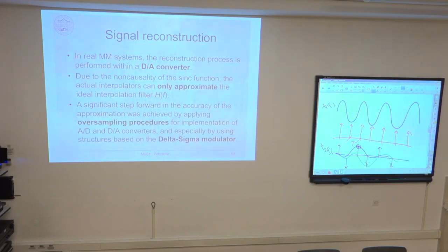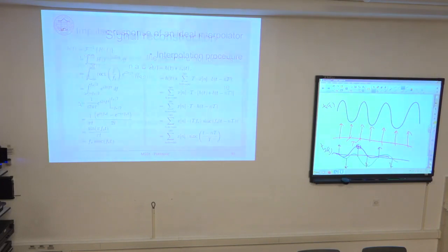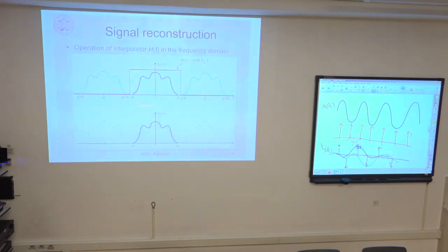So most of the filtering required to do this brick-wall filtering of the spectrum is done digitally, and only the last part is done in analog, with some RC circuit. So they have only a passive filter with one capacitor and one resistor to do the final analog filtering.